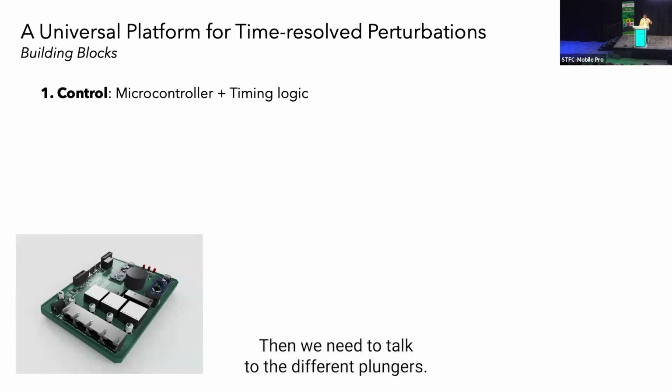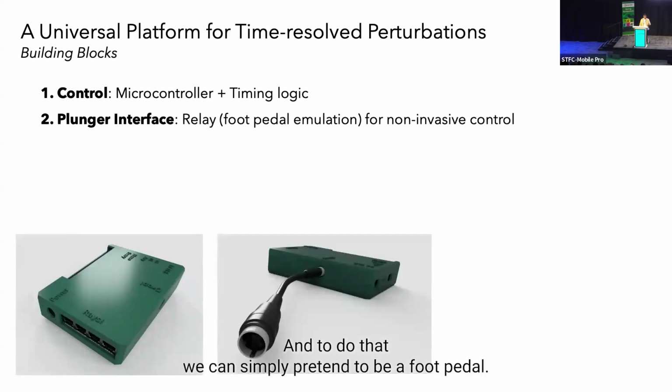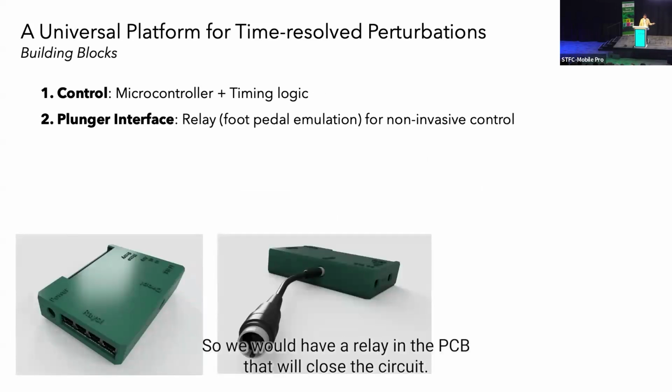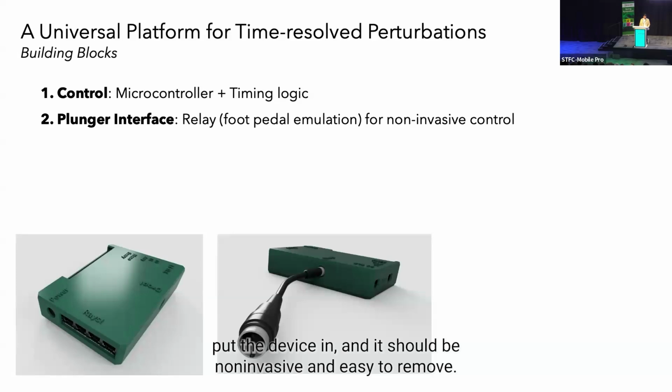Then we need to talk to the different plungers. So we need a universal system to interact with all of them. And to do that, we can simply pretend to be a foot pedal. So we would have a relay in the PCB that will close the circuit. So all you have to do is unplug your foot pedal, put the device in, and it should be non-invasive and easy to remove.